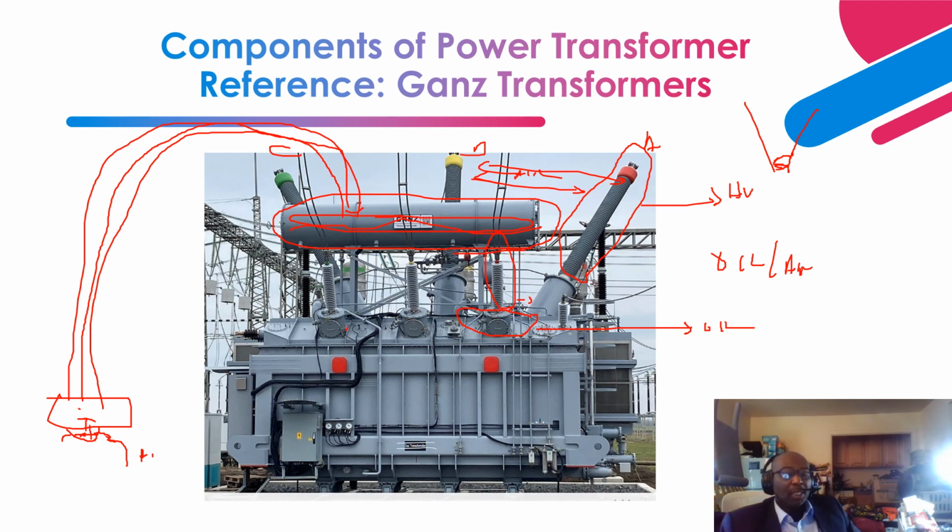Okay, so this is the low voltage winding bushing. And inside here are your bushing turrets, T-U-R-R-E-T. And inside here you have the CTs. You can have about 2 or 3; usually they put in spares. You can have one for metering and one for protection. These are all wired and go to the control cabinets. So this one is for phase A, phase B, phase C.